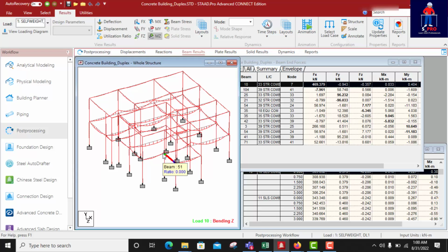Okay, I think we will stop here. In our next class, we are going to be using RCDC to design all these concrete members. We do slab design with RCDC and provide reinforcement. We also do beam design with the same software and provide reinforcement. RCDC produces detailed drawings. After slab design, it brings out detailed drawing, both top and bottom reinforcement. So what you need to do is just take it to AutoCAD and clean it up, and you are done with your drawing.